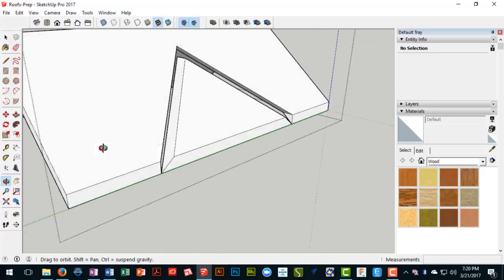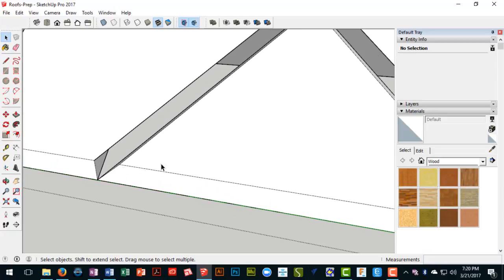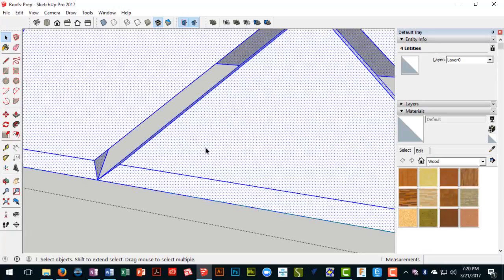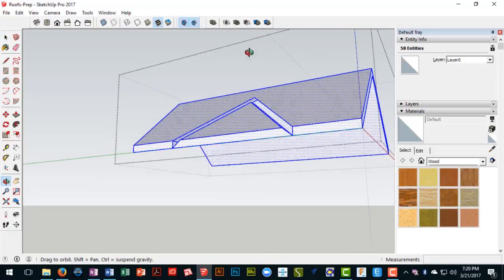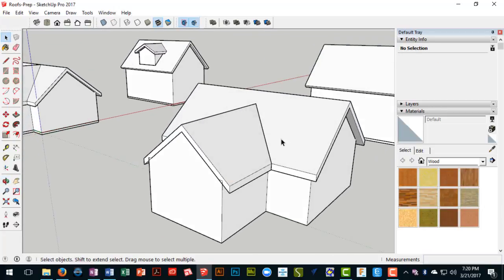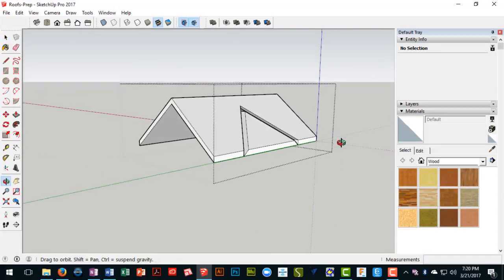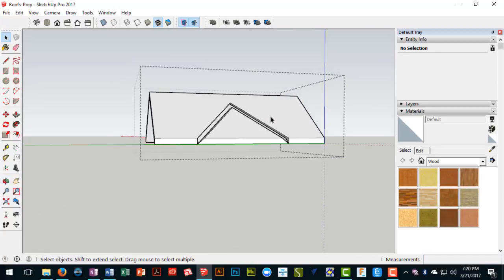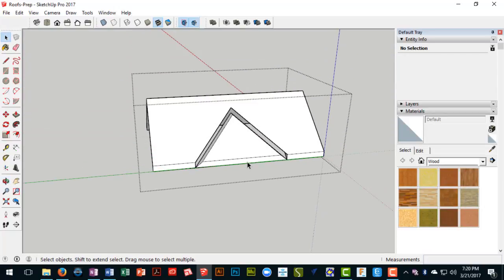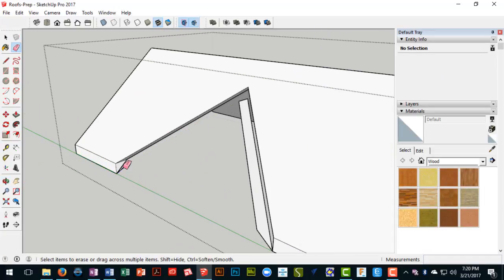We'll click on this roof, and you'll see that I've got a cut piece here. I probably can't triple click on it either, because I end up selecting the entire roof because it's touching here. So I'm not going to, oops, I closed the group, so I'm going to double click again. And the reason I can see all this is because I used my hide rest of model hotkey. So I will go with my erase tool and just start erasing some of these lines that are extra.